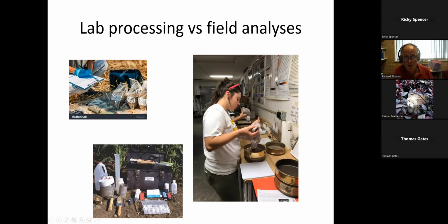It's so easily overlooked, but you have to be organized, because you've just got bags of soil coming back to the lab. You've got no idea intrinsically where they came from. Make sure you've got where in the field they come from well marked out. Now that's a lot easier now. We've got GPS, so you mark where you are in the field, but also the depth, because soil will change with depth. So you need to get the depth profile written down, and so good documentation, because it is so easy to lose track of what the soil samples are when they get back to a lab.